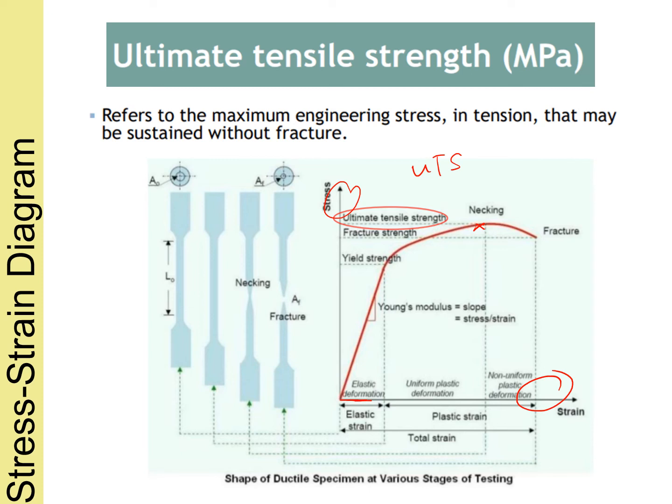If you can see here, before the break it shows necking. So what does necking mean? Before the necking, there is a region that shows strain hardening. As I mentioned just now, we have the upper and lower yield strength, and this is the beginning of strain hardening, where you have the ultimate stress while the specimen is elongating.